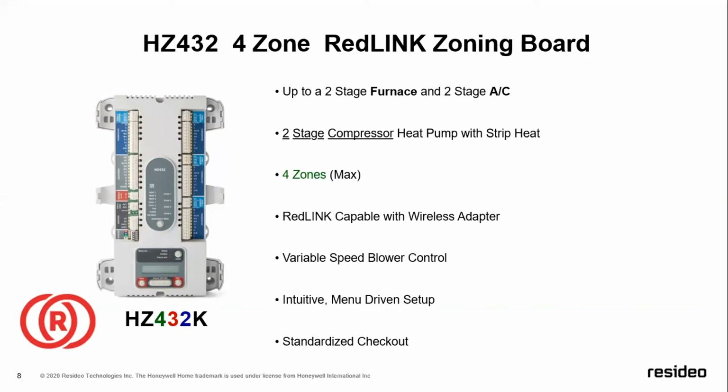So here's what the Honeywell engineers have done for you. When you only have a call for 1 zone on an initial startup, we powered down that DSBK terminal. We take the 24 volts away. So what that means is, with that 65 to 70% airflow, you're not bypassing as much air through your bypass damper.